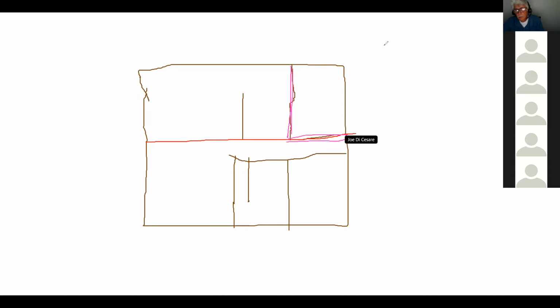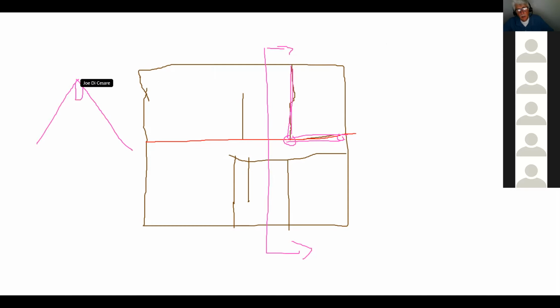Okay. Yes. So the wall might not be load bearing, but all of a sudden there could be a column. For example, if I do a cross section here, what I'm trying to make you understand, if I do a cross section here, you told me that this is what you have. You said that you had rafters and you had a big beam in here that's supporting your roof. You understand? And you were saying that that beam goes from there to there, and I said very unlikely that it's doing that. Unless this is a big glulam that can actually span this. If that's the case, well, that's the first thing you have to do.